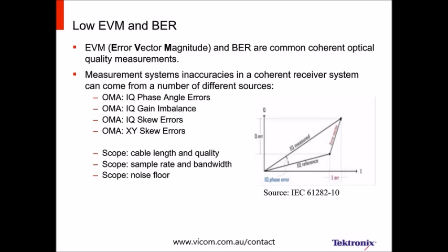But there are other standards, for example, the IEEE, the wireless type standards, they put the sort of average power in the denominator. So there's at least 2 different definitions of EVM floating around. The most popular for optical, because of the IEC, is to use the largest symbol in the denominator.